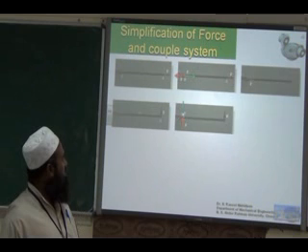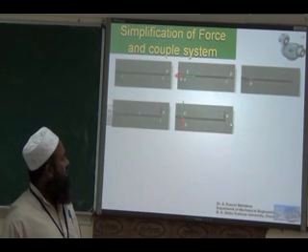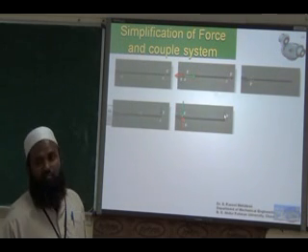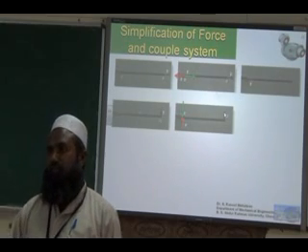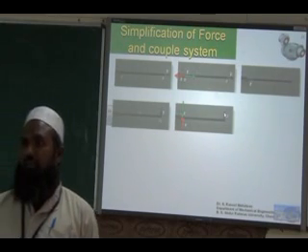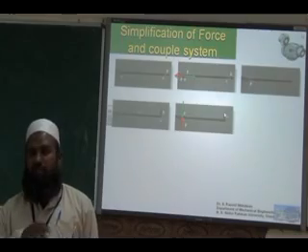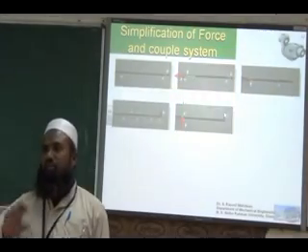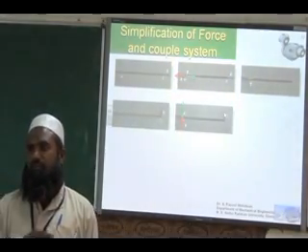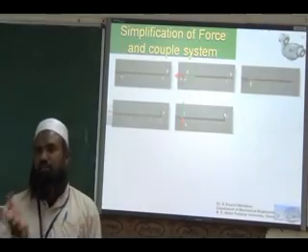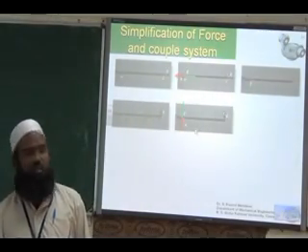We apply two forces equal and opposite to the force at point A. So the forces in opposite direction get cancelled. This force and this force will get cancelled, but it will introduce a couple now. In the process of cancelling the force at point A, we introduce a couple. So we have a force and couple. Now it has been changed into a single force and couple system.